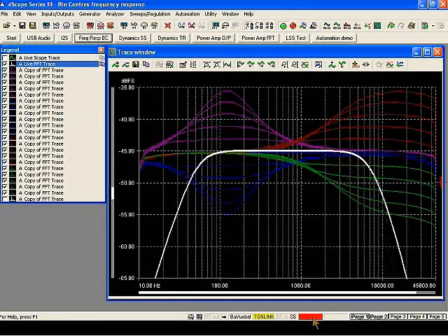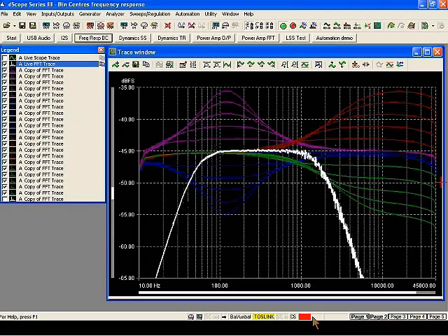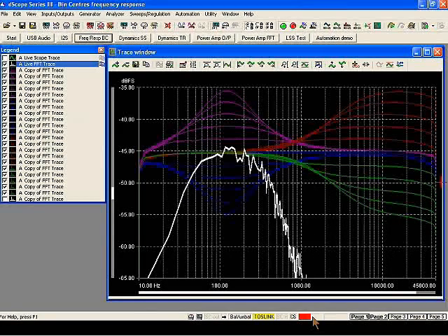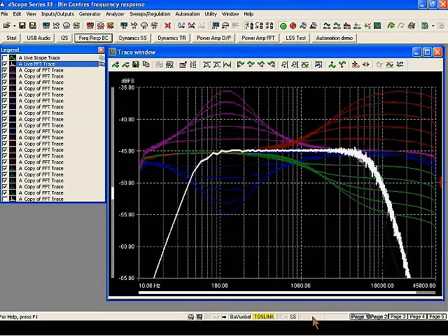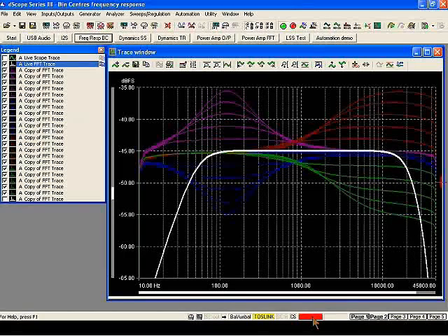So I'm making some adjustments here, and hopefully you're seeing quite clearly just how quickly those individual frequency responses are updating. So this is a really, really powerful tool if you need to do a large amount of analysis on a system that perhaps has some variable EQ, whether it's bass management or adjustable crossover slopes or anything that needs a large number of frequency response curves to be verified as part of the analysis process. So I'm just playing with the low pass filter now.